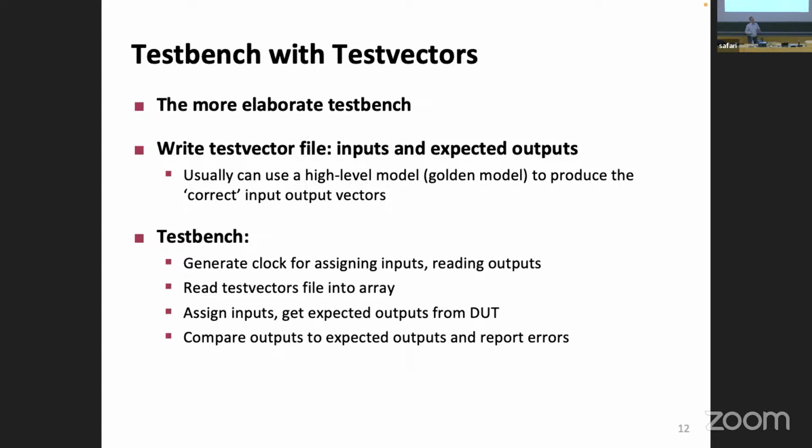Now, there's something useful in using only one clock edge, because we only have to care about the rising time here. Whenever this thing rises, we do something. We don't really care what happens when the clock falls. But we want the clock to rise again, so at some point it has to fall, okay?